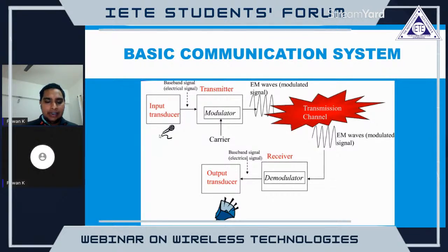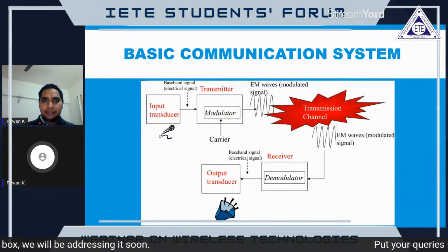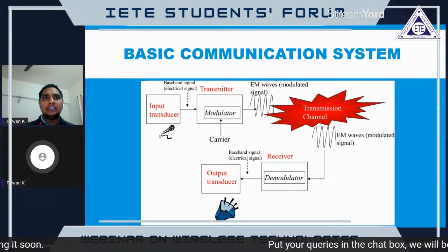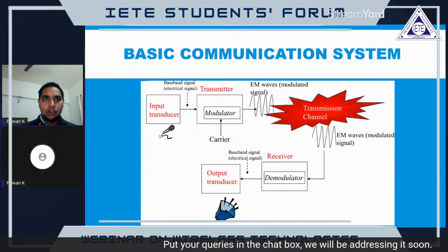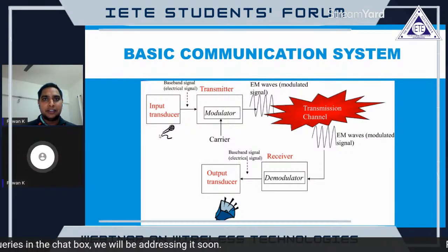After that, the electrical signal will get modulated. Why? The converted electrical signal is produced at a very low frequency. If the frequency is very low, the signal won't be able to travel far, because it will get distorted, and the receiver will not be able to hear it, or enjoy what the transmitter has sent. So our first job is to convert the electrical signal we got as the output of the transducer to a high frequency signal.